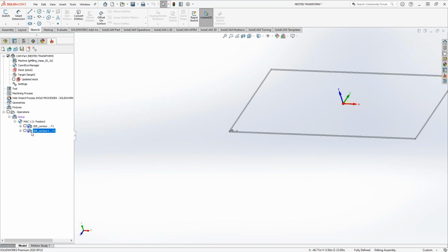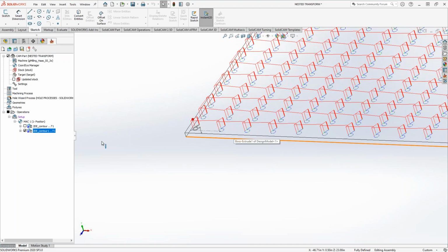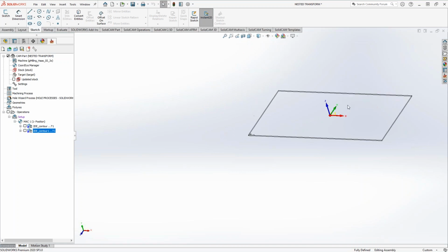Now, I'm not sure if that's coming through well on the GoToMeeting, but next to the one that is currently just a transform, so this is just transforming the letter 6, it has a little T next to it. If it was a rotate, it would have a little R next to it. If it's a 4th axis, it would have a little 4 next to it. So there's a lot of stuff in there that will indicate what's going on with that particular toolpath. And since the first one is both a rotate and a translate, now it just has an X, indicating that there's at least 2 types of transforms applied to it.